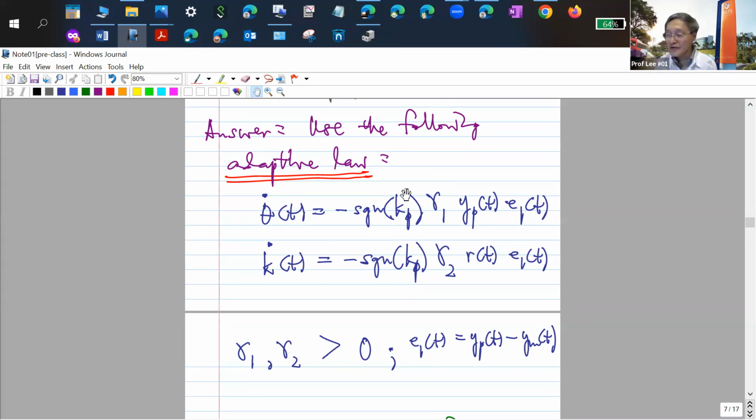Mathematically, it removes that, but in terms of real performance, replacing it by a Nussbaum gain, although it solves it theoretically, your performance deteriorates. Because what the Nussbaum gain does is that it basically searches in both directions. In fact, when it comes to a multi-dimensional system, it searches in n space. You can basically project it from signals on a torus. Not only does it have to search in the entire n space, as it progresses it has to search faster and faster. So it's a lim sup, lim inf kind of problem. It's quite interesting.